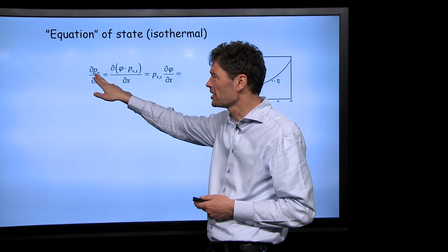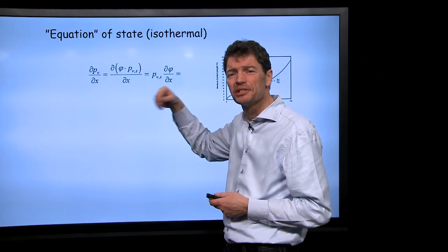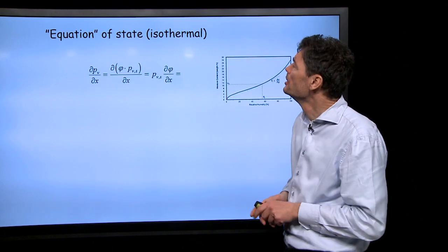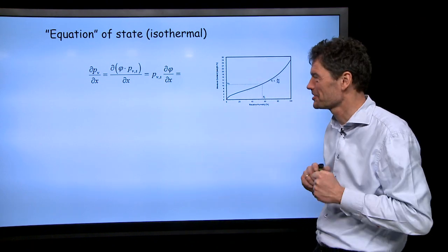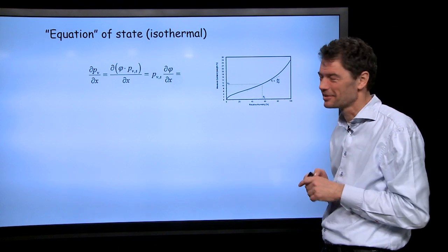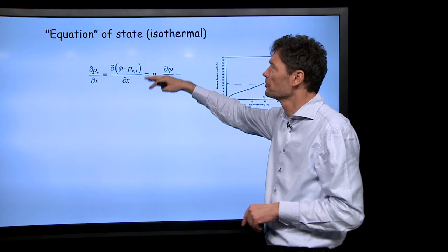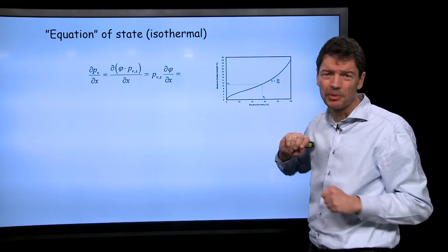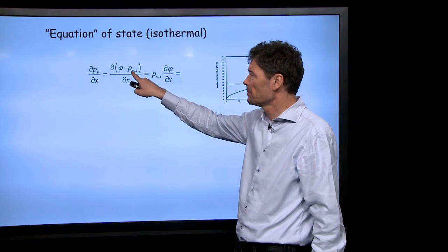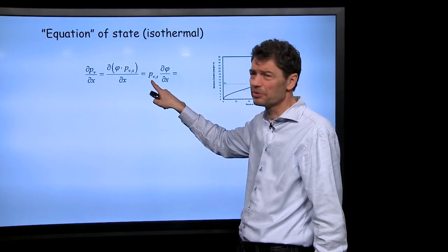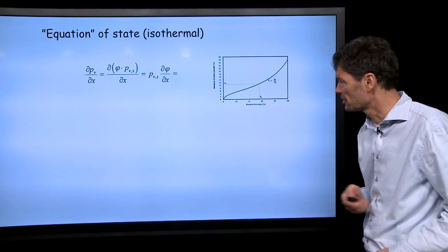Now, that means that from the equation before, we can work with phi, actually. We used to work with vapor pressure, but vapor pressure is the relative humidity times the saturation vapor pressure. And the saturation vapor pressure is something that is determined only by the temperature. So there's a potential for some coupling there between vapor pressures and temperatures, as we'll see. Now, at first, on this slide, we're looking at isothermal conditions. So yes, we must know the temperature, but we assume it's constant, it's isothermal.